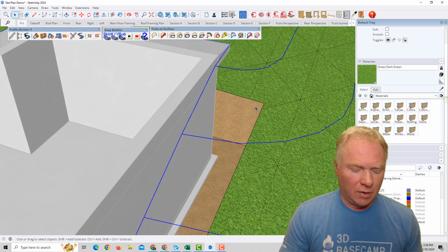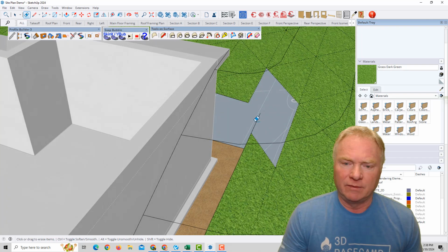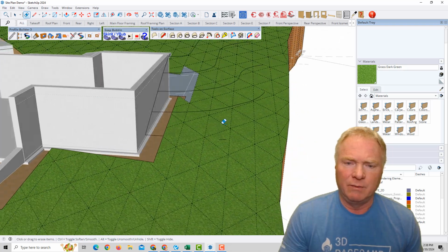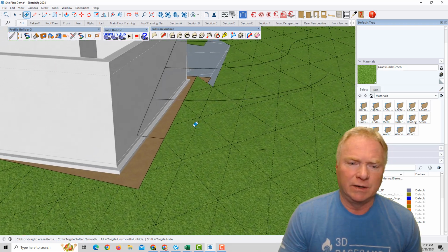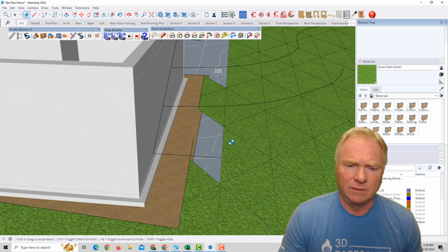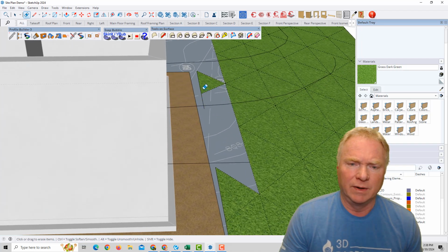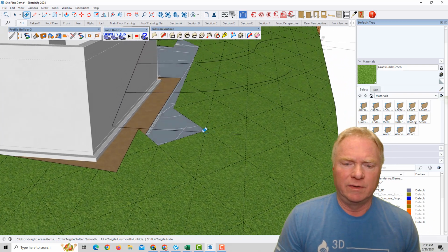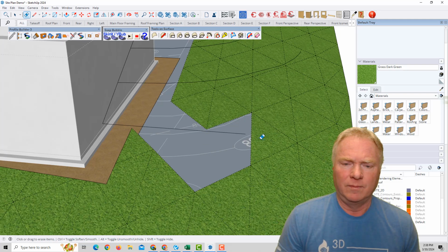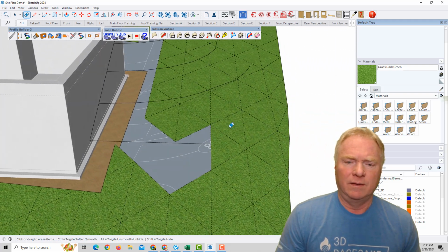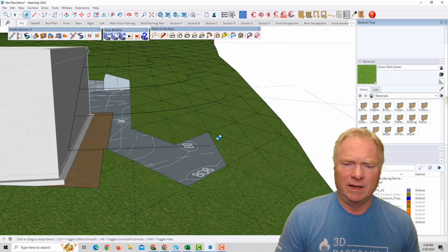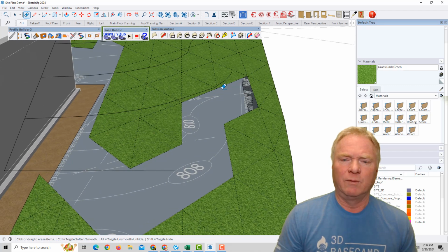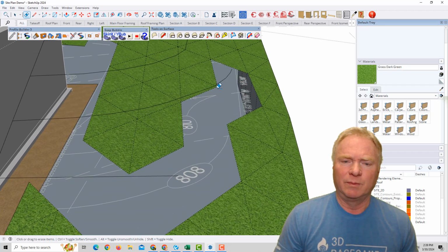All right, so I'm going to just start by getting rid of this excavated edge, because we're not going to need that, right? So I'm just getting rid of the grade that we're going to change here. I'm going to get rid of it down to about in here somewhere, where we were joining over to this other line, to that new grade. All right, and you can see how it's going to intersect over into there. I'm going to go ahead and just take out a few more sections here, because we're going to rebuild this property here.